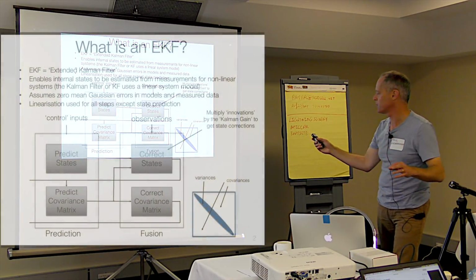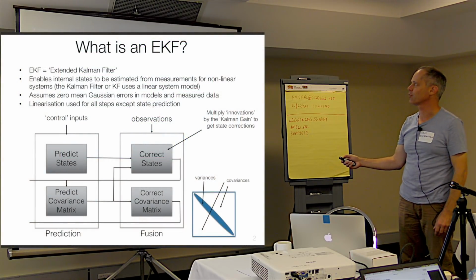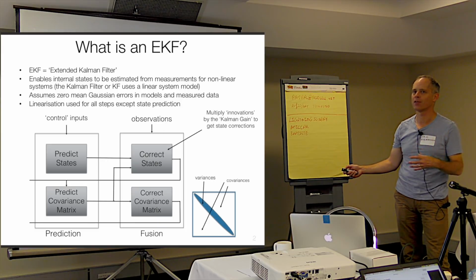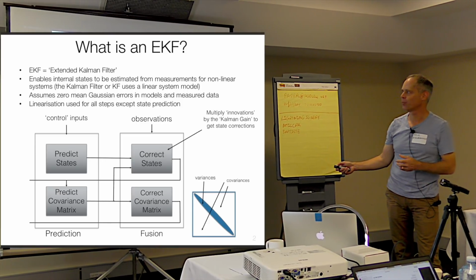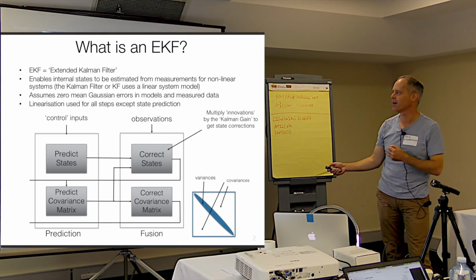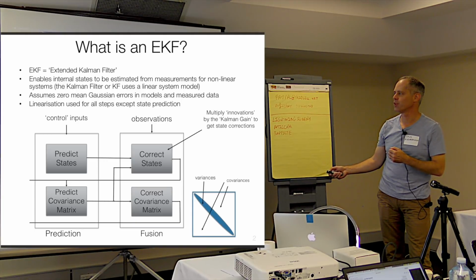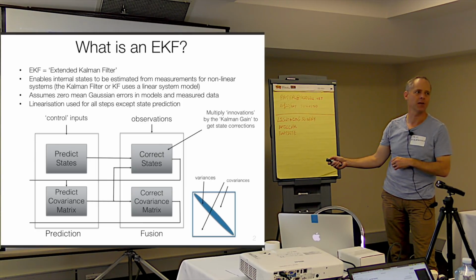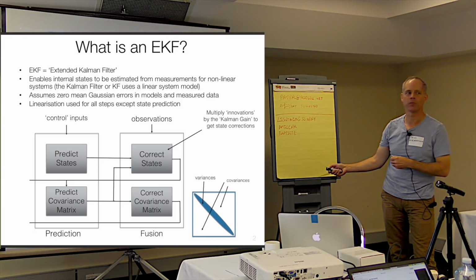What's the EKF? I won't spend much time on this. It stands for Extended Kalman Filter. It's a mathematical technique that makes assumptions about errors on different sensors and tries to combine them in a statistically meaningful way. It predicts forward in time using the IMU data. It also tries to predict what the errors are. It's a big matrix which represents the errors, called the covariance matrix. It then gets observations from your barometer and your GPS and your magnetometer and your optical flow, and then it corrects the prediction from the inertial navigation system, and it also updates your estimate of the errors.